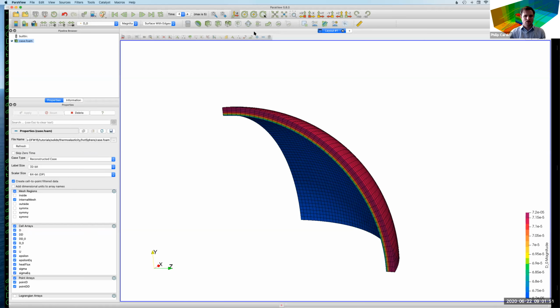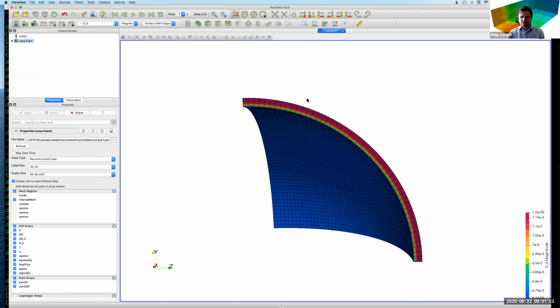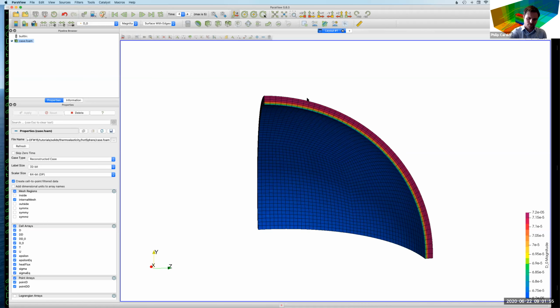Also, which people find a bit confusing in solids, is the small strain approach. Maybe you're not familiar with that, but there's two main ways to model it. If you open finite element software like Abaqus, you have to choose if you want a large strain or small strain approach. It's also called a nonlinear geometry or linear geometry approach, or NLGEOM in Abaqus.